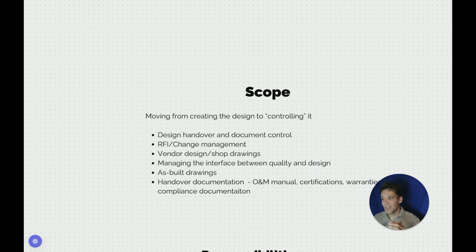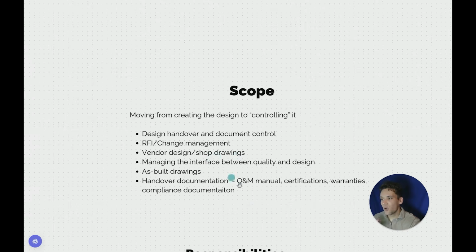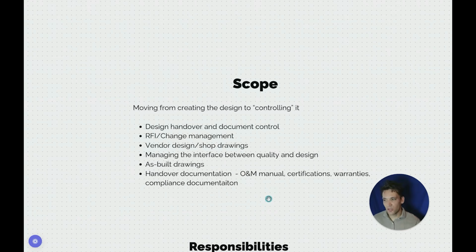They're documenting any changes, or they're working with the construction team to capture all the changes and develop the as-built drawing set. They're also preparing the handover documentation. Typically, the design manager is also the one preparing the O&M manual, certifications, warranties, compliance documentation, getting it all together to submit at the end of the job.